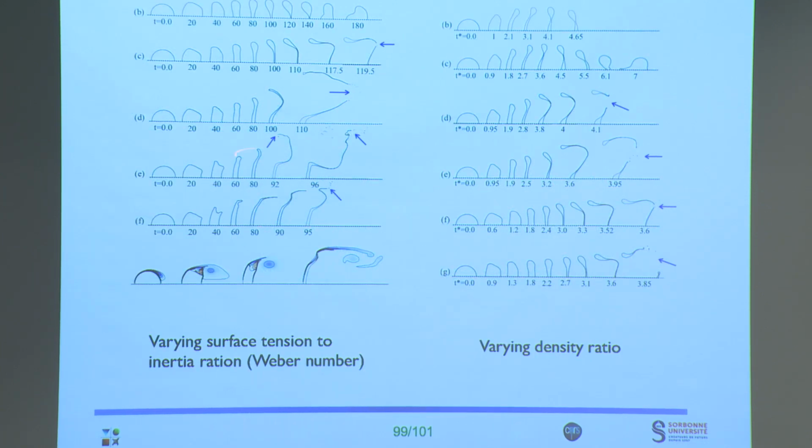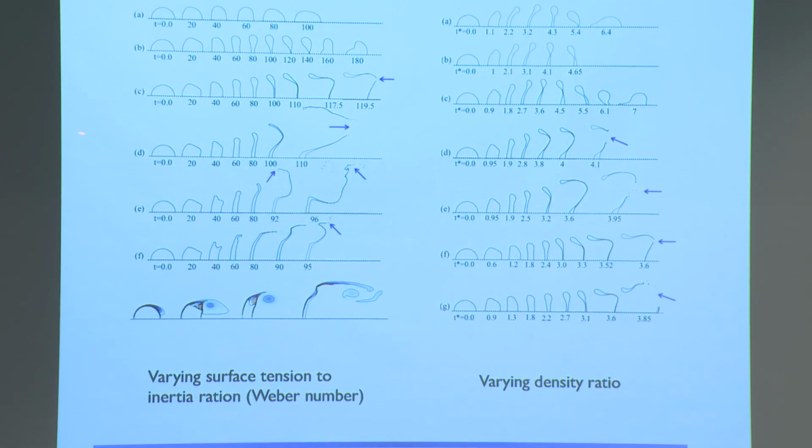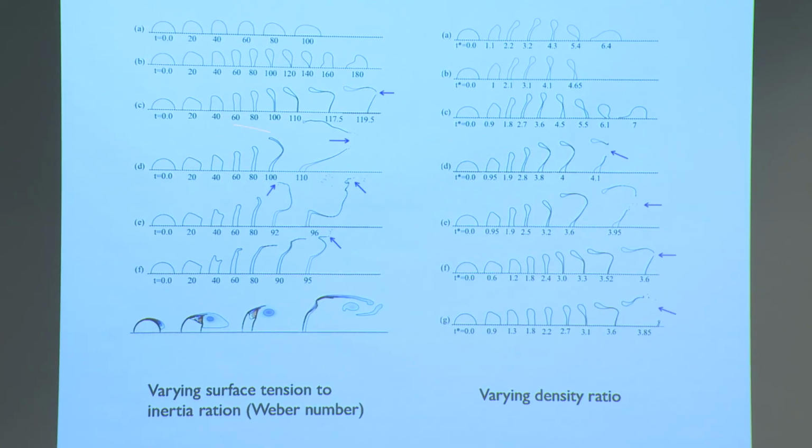This is a very nice work we did with Florence Marcotte, where we studied this. I mentioned bag atomization, so the wind will also blow a bag in the droplet, which is what you see. We did it for variable Weber numbers and for variable density ratios. You see the density ratio has a small effect. You don't see quite the same shapes, although they are similar. Basically, it expands more with the largest density ratios, here about 1,000, and here the smallest, about 10.